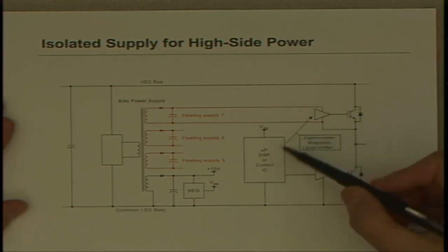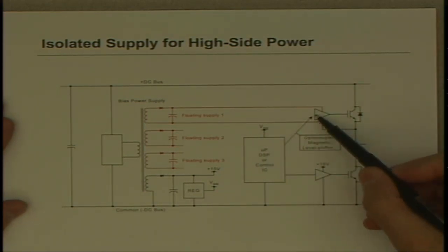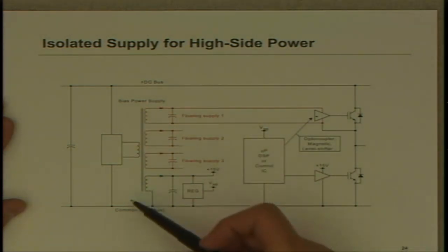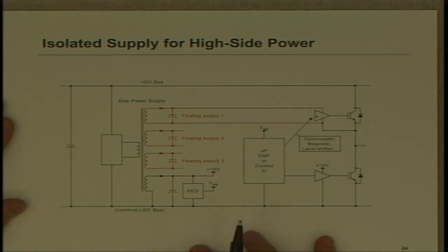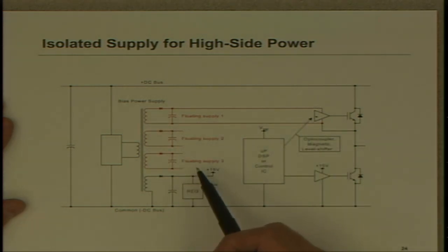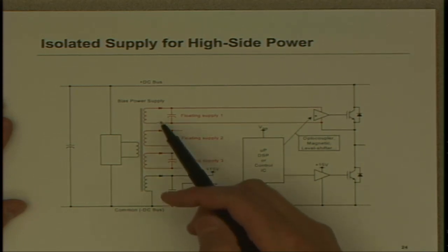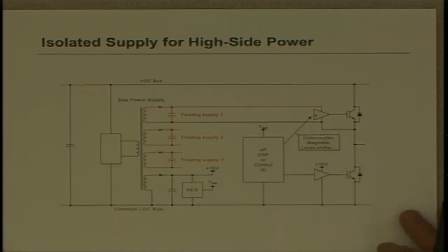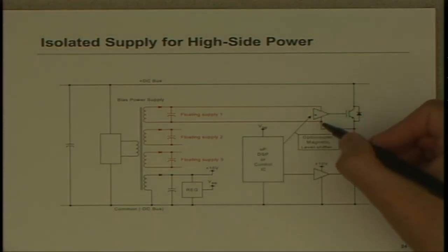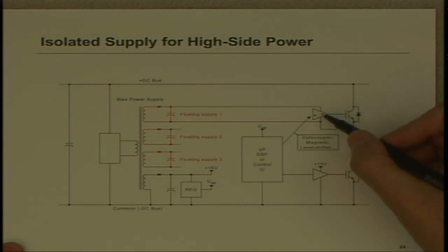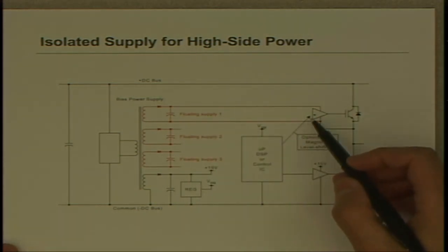One question though: even the transformer, it's not sending power, right? It's only communicating from your controller to tell the device to turn on or off. You still need power for the high side gate drive. One way to do that, if you have a bias transformer, like a little housekeeping flyback supply on your drive or inverter, whatever it is, you can add little separate windings here and have one for each of the floating high sides. The penalty is, it seems easy enough, but because of creepage and clearance distances required, the bobbin and everything gets larger, and the transformer gets more expensive. So this is not the cheapest way to go, but it does provide a nice stable DC floating voltage. So you can turn the high side on indefinitely, right? I can go to 100% duty cycle, and it's always got power because the power supply is driving it.